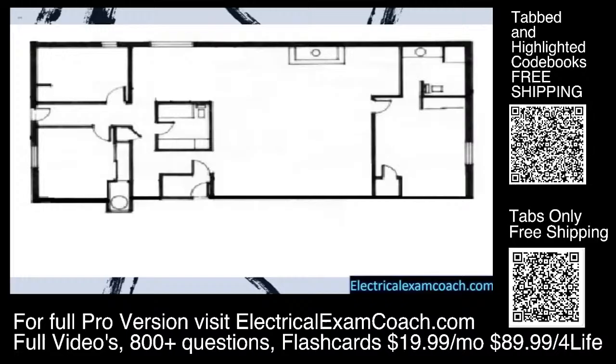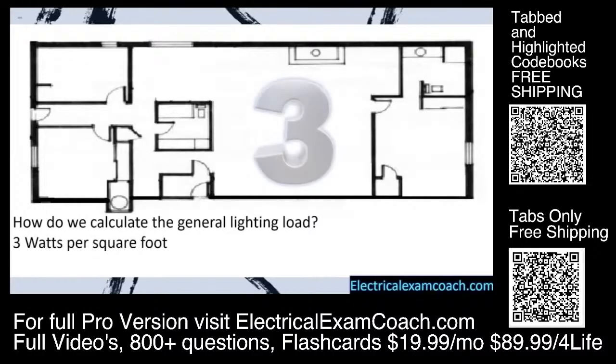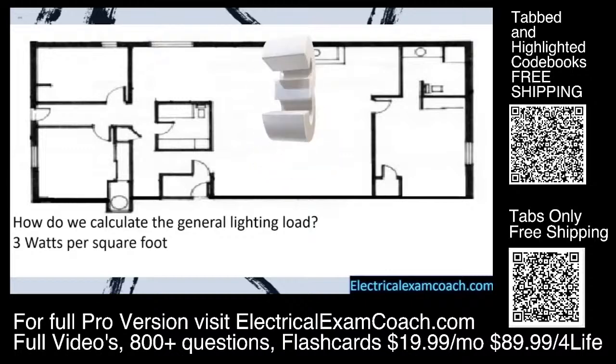The first question we have to ask is, how do we calculate the general lighting load? Are we going to calculate it per receptacle outlet, per lighting? Do we have to count them, add it all up? Thankfully, no, they've made it very simple. So we're going to calculate it at 3 watts per square foot.